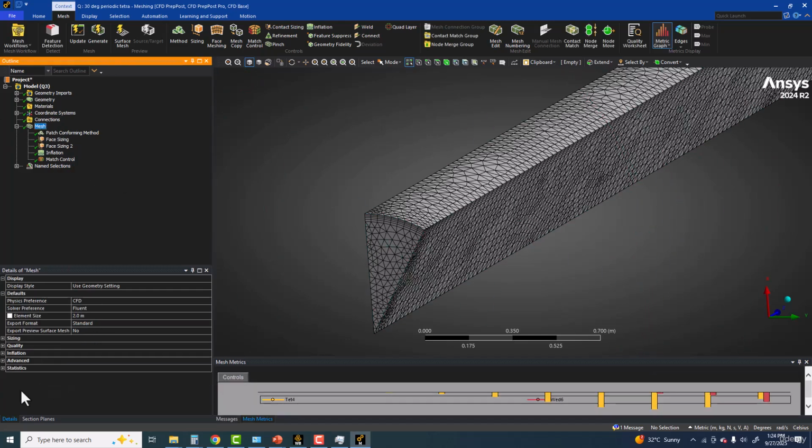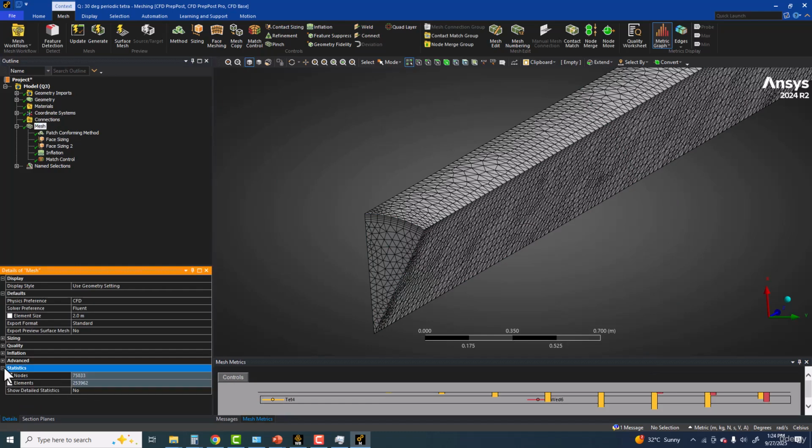And the number of cells, you will be surprised to see. Elements are 53,000, same as a 3D mesh. So this is a problem with the 2D mesh, especially when we are getting the triangular mesh. If you go for the hexa meshing, the number of cells will reduce by substantial quantities. Still, we have to make some cells there to represent the geometry and the flow properly. But that's, I would say, maybe 1/10 of the mesh size of this one.